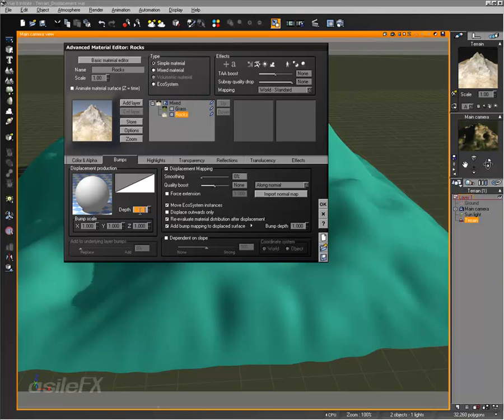So I'm going to force this depth amount to, let's go ahead and type in a value of 10. And the new option is to control the direction. We have along normal, horizontal, vertical, normal map, and custom mode. Along normal is the default. If you're not familiar with normals, they're basically the direction a polygon face is facing.